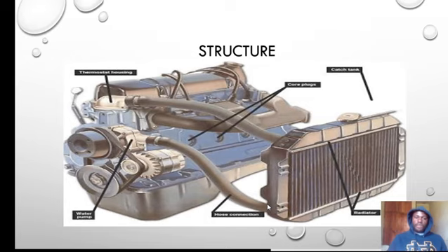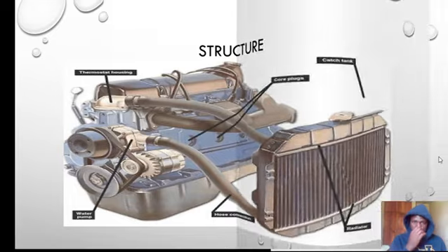So remember, the water will be flowing by the normal principle that hot water will be less dense, and therefore the cold water will be denser. So the cold water will move from this point. As it comes this way, it will flow all the way, and after it rotates through the water jackets in the engine and cools it, it will become hot and therefore less dense and rise, and again come to the radiator. And now in the radiator we have what we're calling the fins, and the fan on the other side. It will cool the water again, and the same process continues.